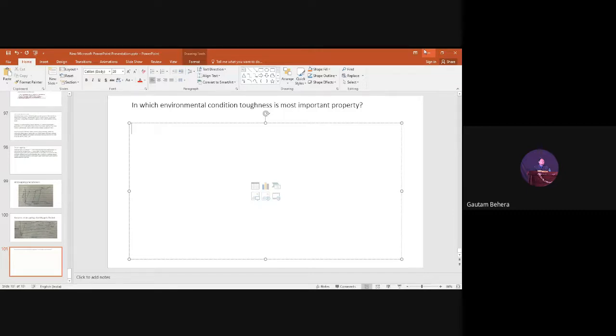Due to brittleness of the steel, it cannot absorb the energy. So you understand what is happening. Was the toughness low or high in that condition when it got fractured? Low, sir. Obviously, that's why it gets fractured. This happens due to the ductile to brittle transition. In earlier days people didn't know about this ductile to brittle transition happening in materials. The crack initiated, the water went inside and the ship sank.